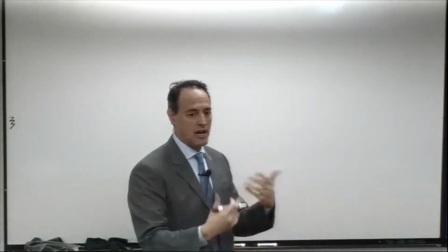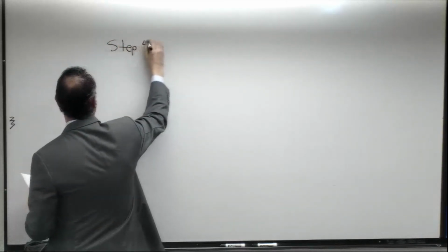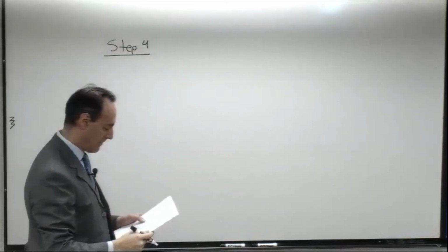And as the dynamics changes, you can just keep changing the matrix A, right? You can just update the model as you go along. The nice thing about this, it's kind of like a low commitment thing. The model changes, and you're like, no big deal, I'll just build a new one. I can just keep updating A as I go along. Because a lot of systems change on you. So if you commit to a model and it goes bad, you've got to build a new model. This says, I'll build one for you as we go. In fact, I could do it on the fly as it goes along. Okay? So that's something pretty nice, especially for parameterized systems where parameters are wandering on you. You need something that can handle that.